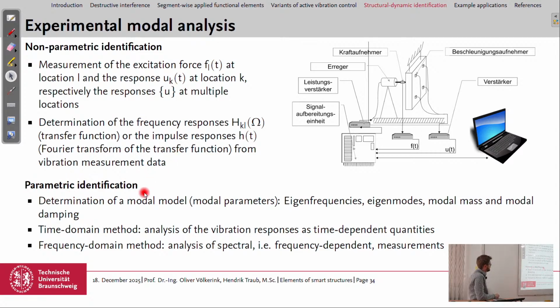And in case of the parametric identification, we really determine the modal parameters, so the eigenfrequencies, the eigenmodes, the modal mass, and the modal damping, and the modal stiffness, which is missing here.